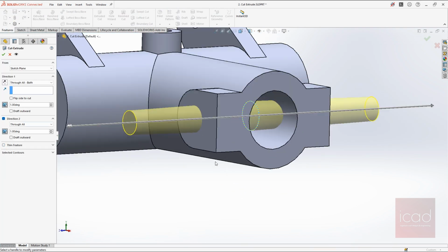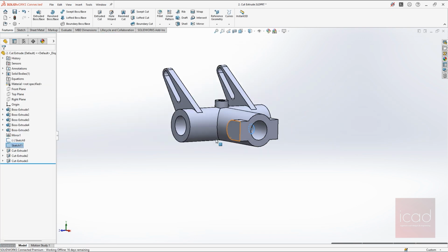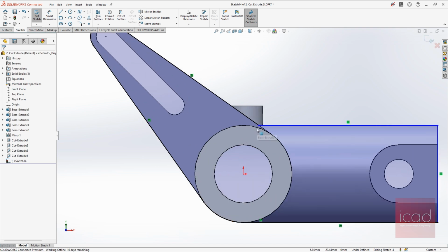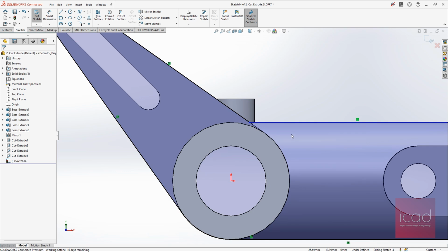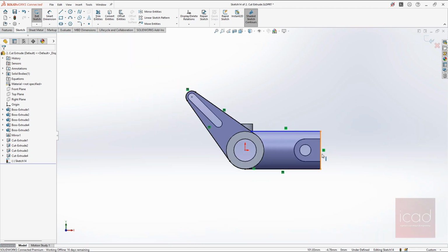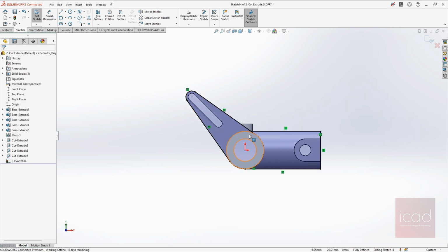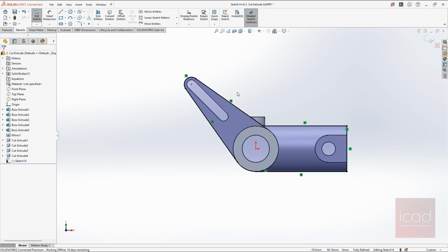Yeah, the last option is, now let's say I have a sketch. As you can see here, I have a closed profile. What I want to do is remove whatever is outside this box. But if I had to delete something outside this particular closed sketch, I would have to draw another small sketch over here, but I don't want to do that. It's too much work. I want to select that particular section and then remove everything.